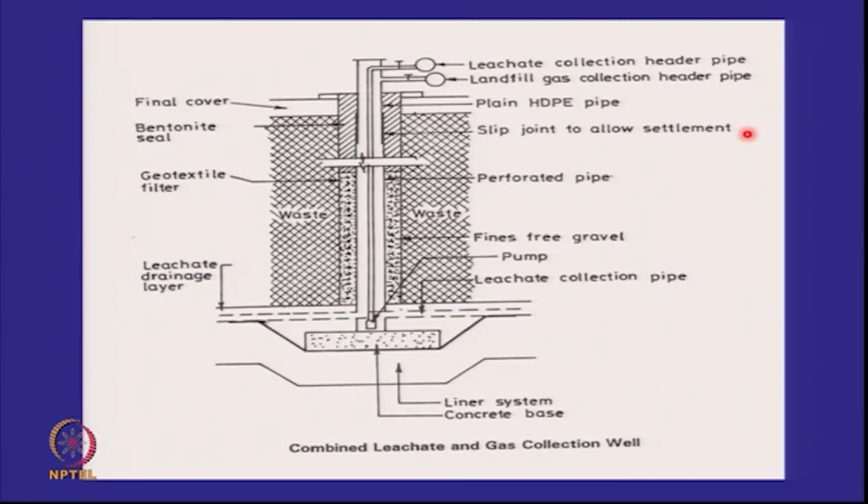This is a combined leachate collection and gas collection well. We will probably look at this at a later date, but the idea is from the same well you can have a submersible pump and take out your leachate, and you can have an outer annular space from which you can collect the gas. And when we do gas collection system, I'll try to visit this again.